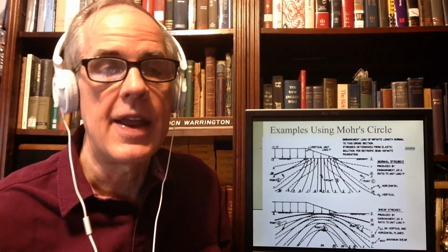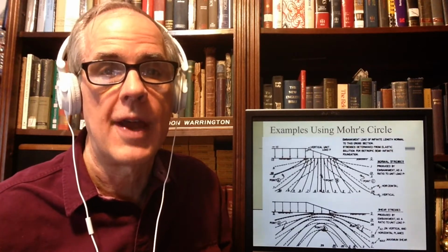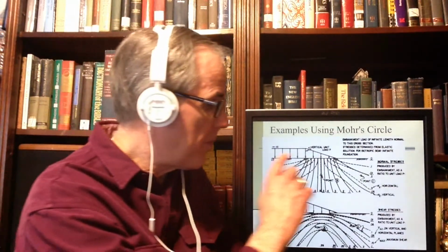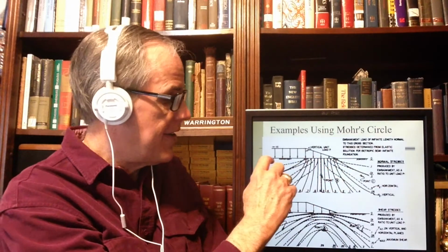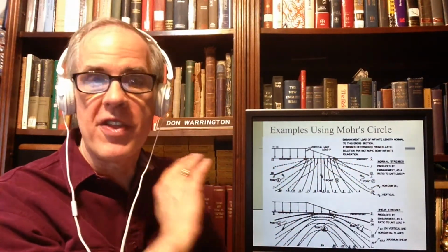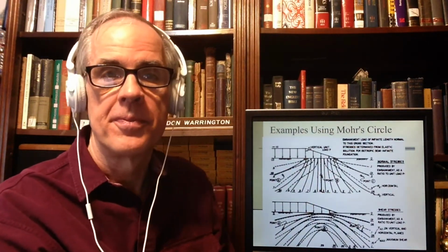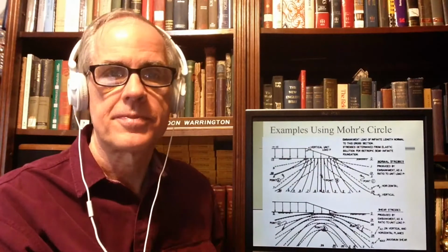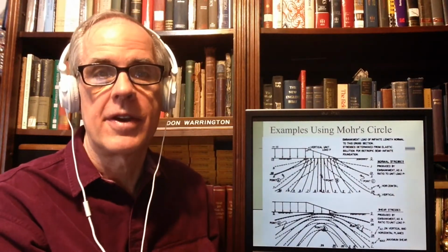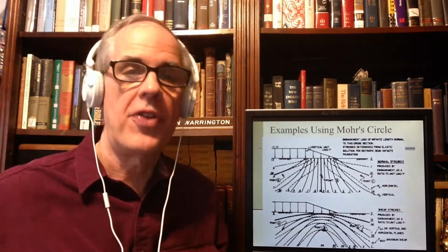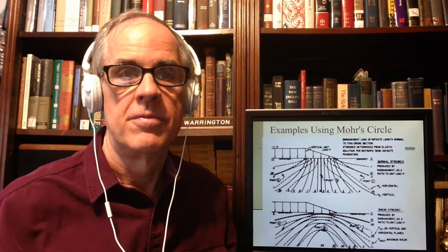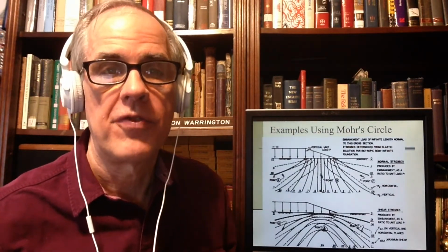That means that 18 kilonewtons per cubic meter times 2 means that uniform surcharge exerts an additional stress of 36 kPa over the entire soil area. And it doesn't have all these funny end effects or side effects. In other words, the whole thing increases. That's the effect of uniform surcharge.